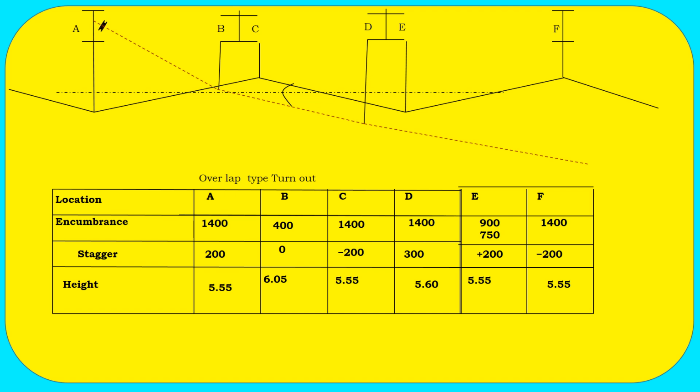Then this is called the obligatory mast, which is a compulsory mast. This is why its name is obligatory mast. And this is the system. You can provide it from a track separation of 150 millimeter to 700. Within this it is adjustable, but better to provide it at 450 or plus minus something, so that it will permit your span,